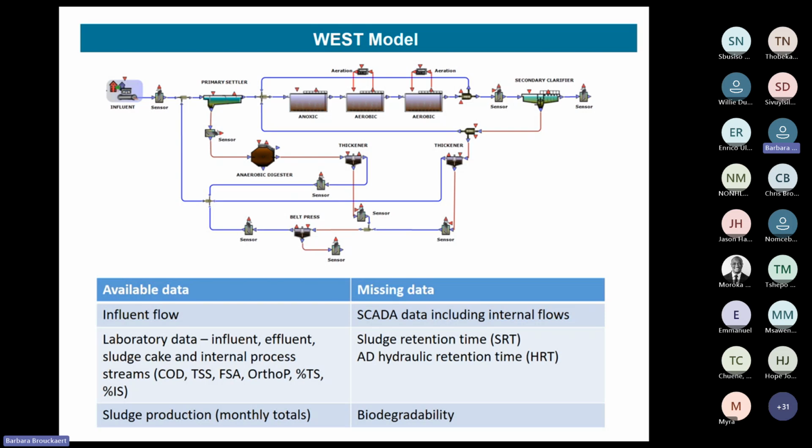But in the meantime, the storage system where the SCADA data was backed up had been damaged. And so that data wasn't available to us. So, for example, we had plenty of laboratory data for different streams, and we had the flow into the plant. But that was the only flow data we had. We didn't have the flow to the anaerobic digesters, so we couldn't calculate the hydraulic retention time. We did not have the waste sludge flow, so we couldn't calculate the sludge age. We didn't have the flow of the nutrient-rich supernatant liquor.